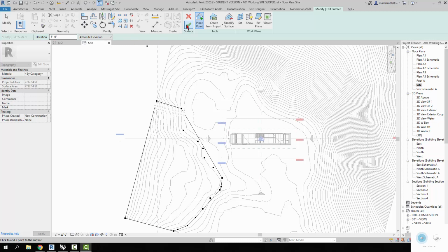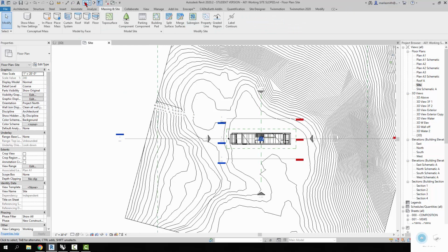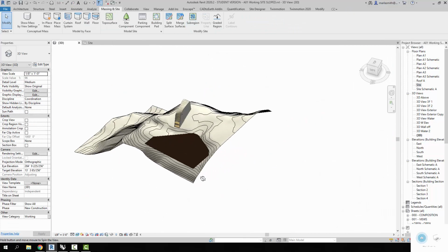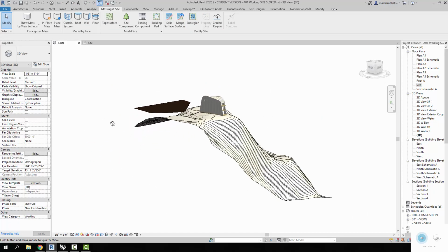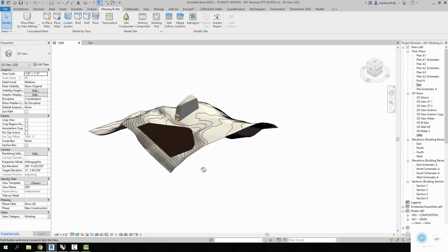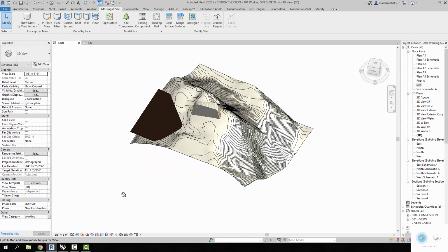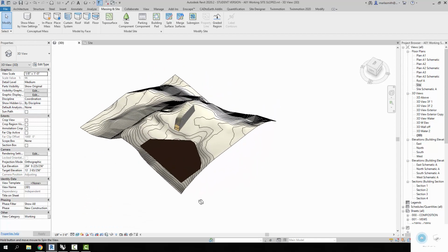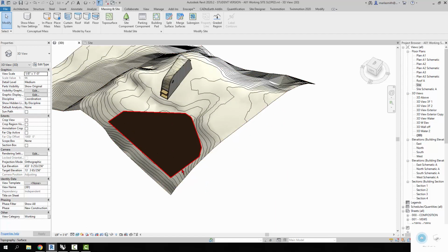I'm actually at -5 feet. It will place a contour at -5 feet. So let's go ahead and check and go to 3D view, and here's that contour occurring. Actually, it's at 5 feet, so it's actually at 5 feet in the air. So I forgot to set my contour points, which I guess is good and bad, but let's look and see how we can very quickly update that.